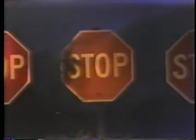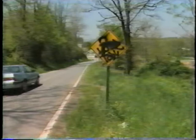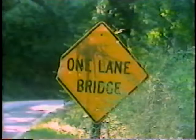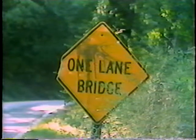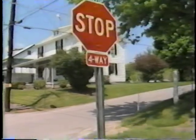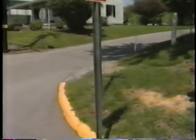We must also face the fact that as our population ages, we'll have more older drivers on the road. Studies show that drivers over 60 need signs that are up to 8 times brighter than those needed by a 20-year-old. The numbers can be intimidating. An Indiana survey of traffic signs on state highways found that 60% were seriously deficient in such important factors as reflectivity, design, size, and placement.